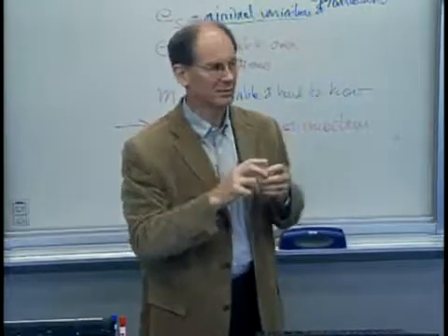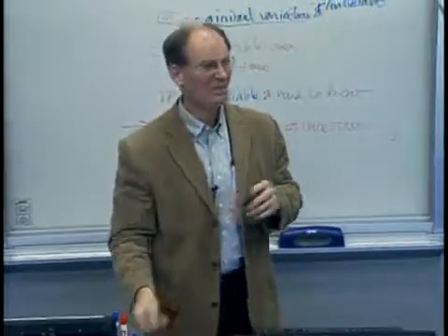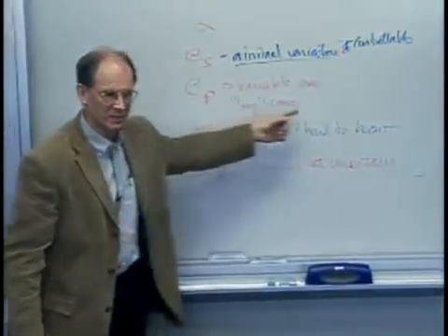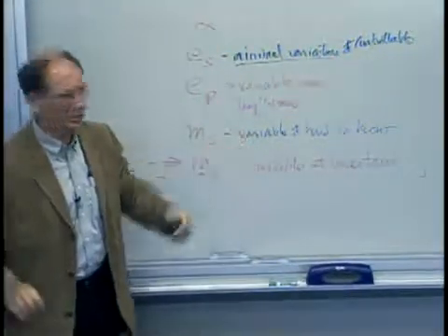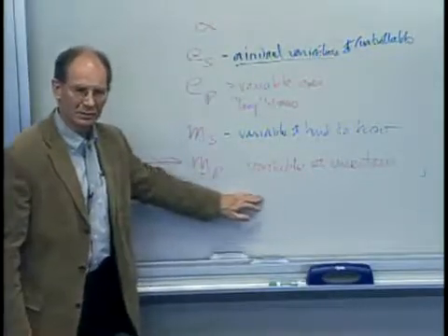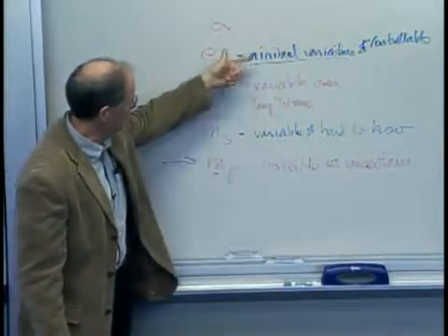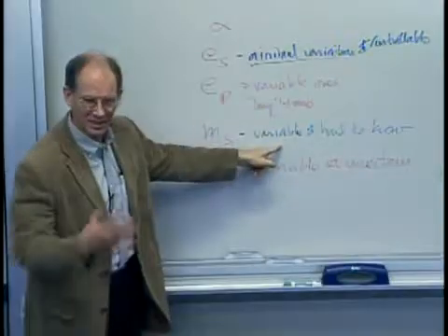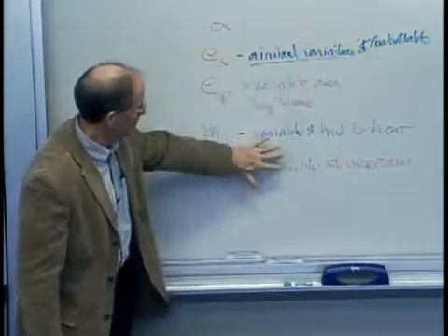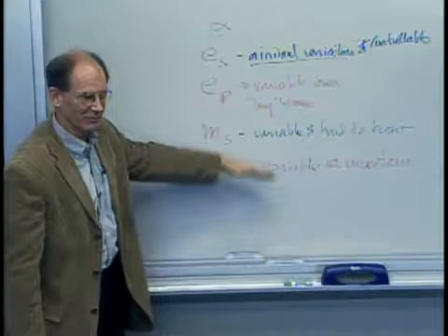And there's also a pressure sensor in the mold. So you could, if you wanted to, actually measure the pressure on this, okay? But it's hard to do. So this tends to be knowable, but sort of expensive to do. So here's the moral of the story. The biggest source of variation tends to be material uncertainties, just inherent in the material, and, if you will, the coupling between the energy source and how well it actually gets into the material through an uncertain interface. So these three are your sources of variation typically, in differing measures.